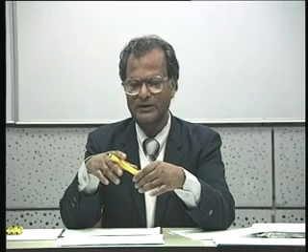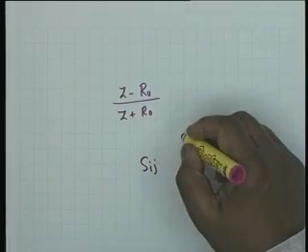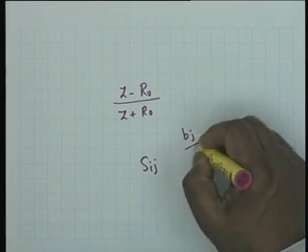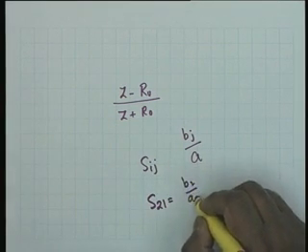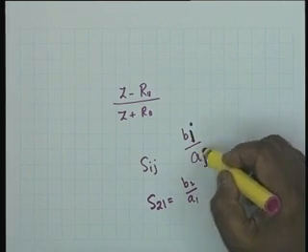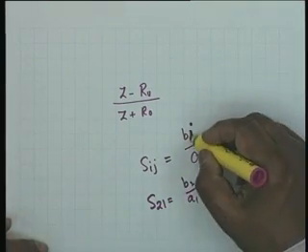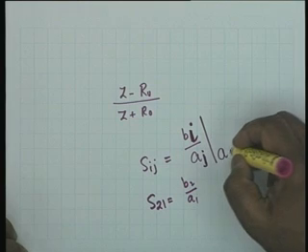They are conditional. Okay. But one thing is sure about scattering parameters, that the numerator of all the parameters is a reflected wave. Isn't that right? Either it is 11 or 22 or 12 or 21, the numerator is a B parameter and the denominator, can you tell me what is S21? B2 by A1. So it is Sij, so it is Bi divided by Aj. Okay? S21 is B2 by A1. Correct. Under the condition that all other Ai's are 0, i not equal to j.